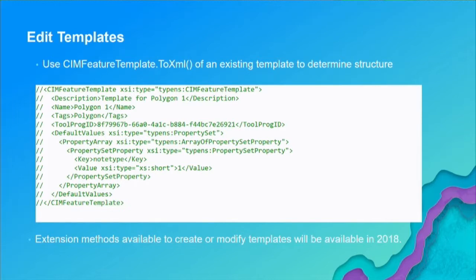We're hoping the 2.2 release they'll be there, so you should just be able to say layer.CreateTemplate, pass in a name, a description, an array of default values, and hopefully a DAML ID instead of this secret little GUID. You're still going to have to define the GUID because that's what the application uses internally, but you shouldn't have to know what those GUIDs are. You should be able to process a DAML ID instead.